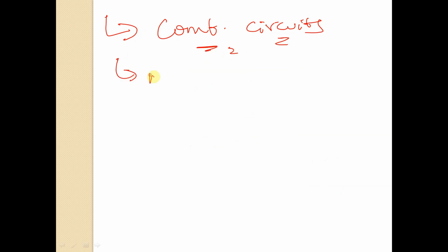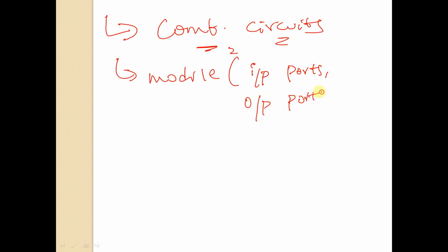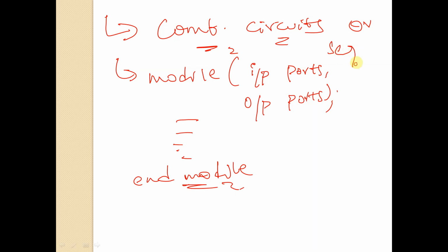So if we have a design in this model, we will have some input ports followed by some output ports, and here we will have our logic followed by end module. So whether the design may be combinational or sequential, we can write the test bench easily for that.